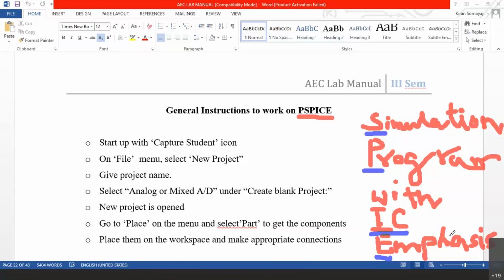But when it comes to BJT or FET, they are non-linear devices. When they are non-linear devices, their complete mathematical model has to be stored in the matrix. And when we simulate the circuit, when we plot x-axis versus y-axis, it is going to take all those values by using those matrices, and then it is going to plot the outcome of the matrix computations as the output response.